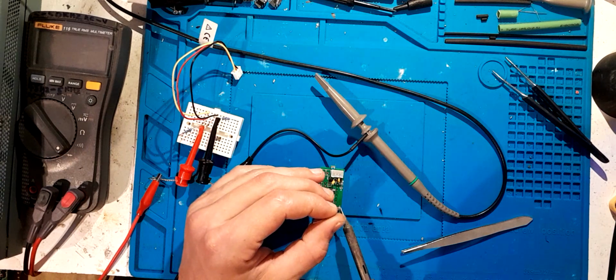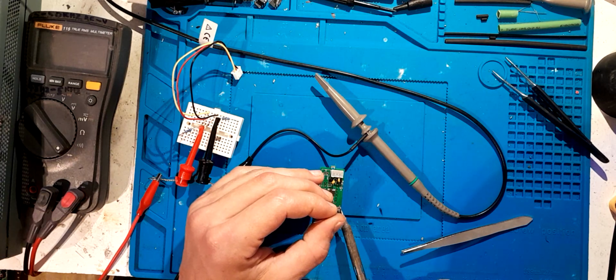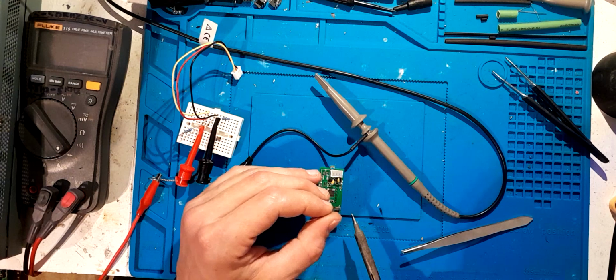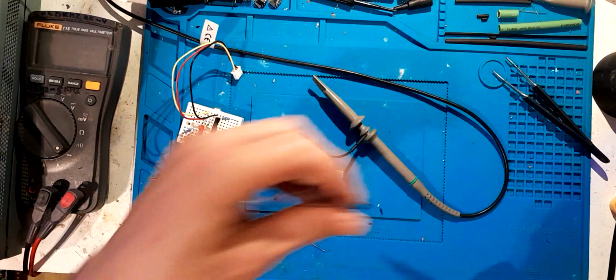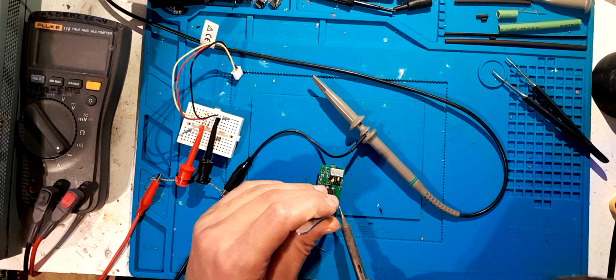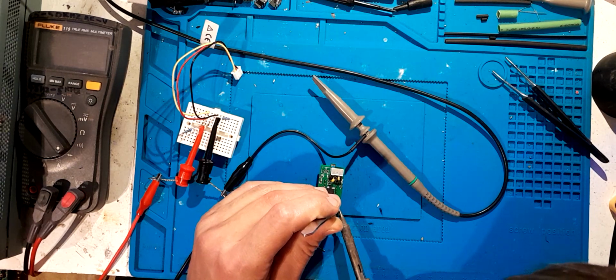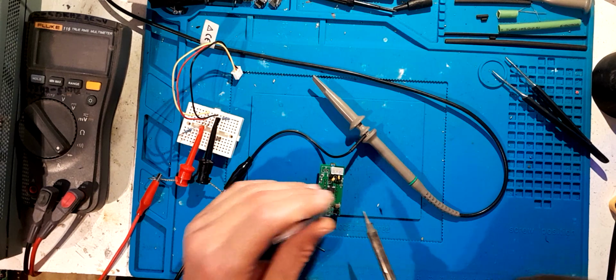So the good thing about stacking ceramic capacitors, or any capacitors for that matter, is every single one that you put in parallel, you're reducing the equivalent series resistance, not just doubling the capacitance. It's almost like building a super cap, kind of.